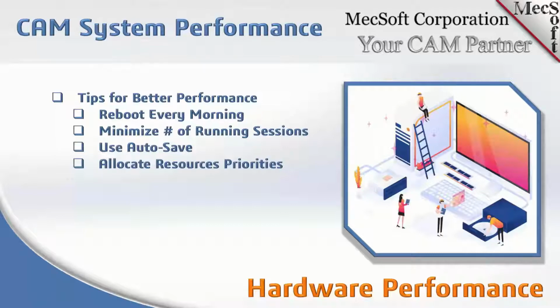And we have done support sessions with users who we discover have got 7, 8, 9 sessions of RhinoCam running, and they're working on one of them. Every one of those sessions takes system resources away from the session that you're working in. So try to get into the habit of only running one session at a time, and that'll be your optimum performance.